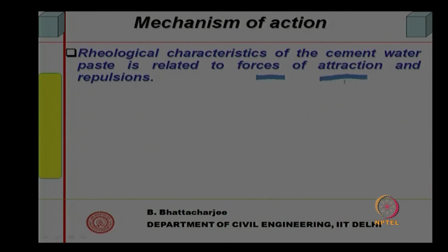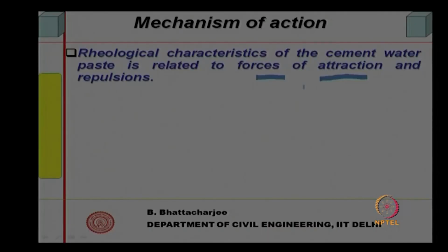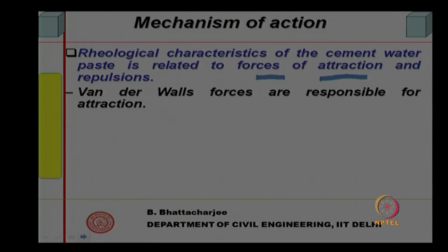So, in the beginning when you add water, the viscosity of that paste that you form, or how much force is required to cause it to move or deform or yield, if I may say so, these are all functions of the forces of attraction and repulsion between the cement particles themselves, right. So, two types of forces of course we recognize. One is the van der Waals forces which are responsible for attractions.